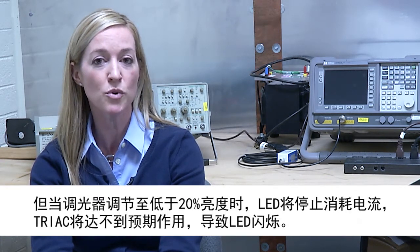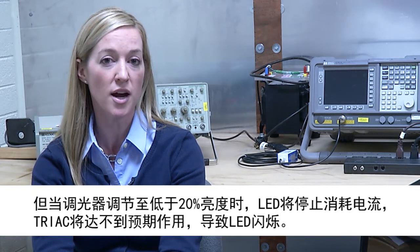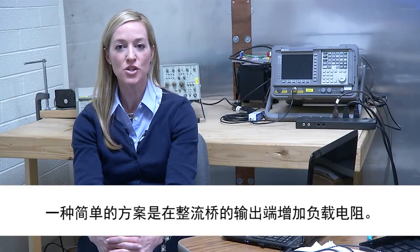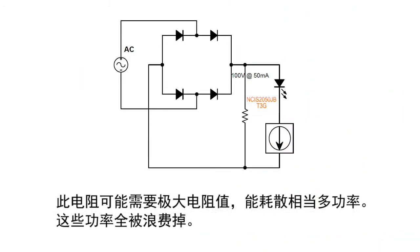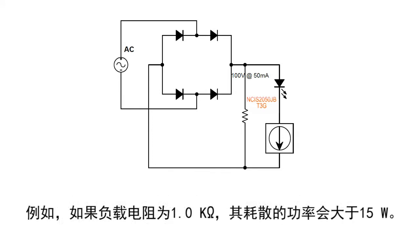The 50 milliamps is sufficient for the triac and the dimmer to turn on and operate correctly. But when the dimmer is moved below 20% on, the LEDs will stop drawing current and the triac will misfire and cause the LEDs to flicker. A simple solution is to add a load resistor across the output of the bridge. This resistor would need to be very large and capable of dissipating a lot of power, which is wasted power. For example, if your load resistor is 1 kiloohm, you will be dissipating greater than 15 watts.